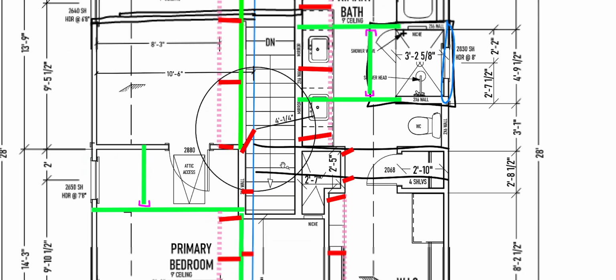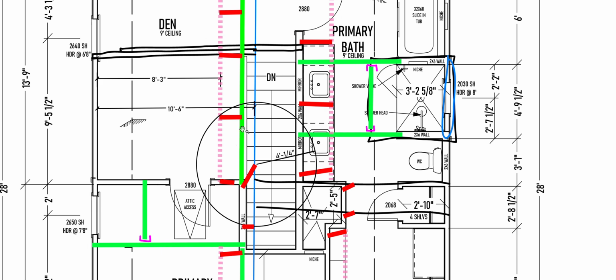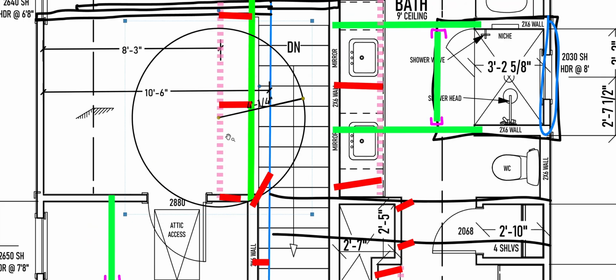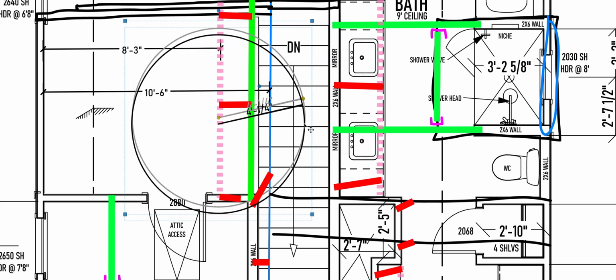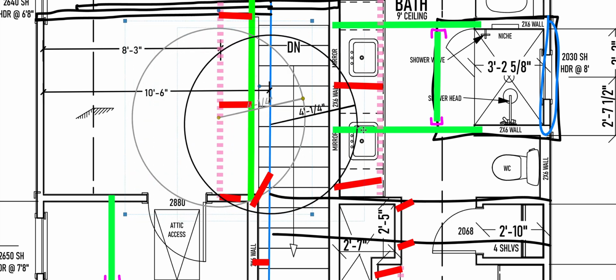So now remember that when I was trying to support this pink purlin right here, I had that 4-foot height to the 9-foot wall. Well, I know that the blue ridge is higher than the purlin because I'm going up the roof, and this 9-foot wall didn't move. So I've got more than a 4-foot range because I went up the roof, and this wall's within 4 feet.